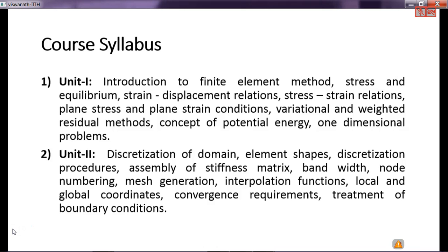The same thing is in the finite element methods. If you end up storing zeros in your memory, you end up occupying a lot of memory in your storage. And because of this, your code becomes slower. So in order to deal with it, there are special storage schemes like banded storage, skyline storage, and other different kinds of things.